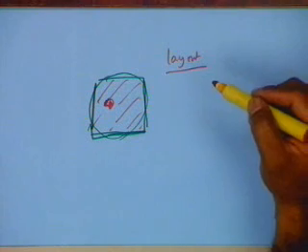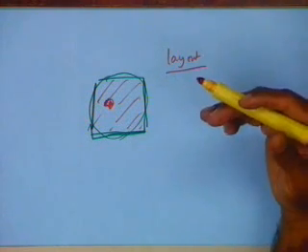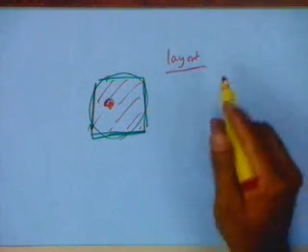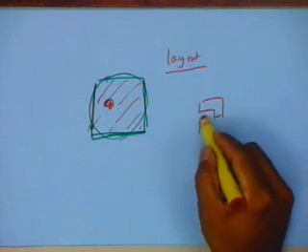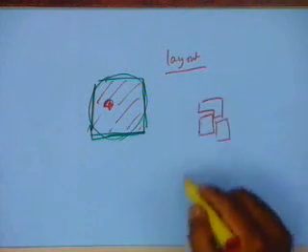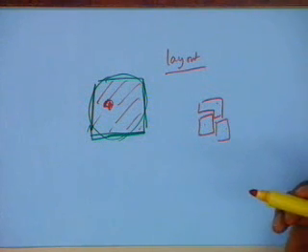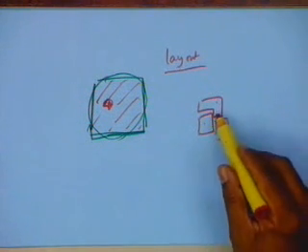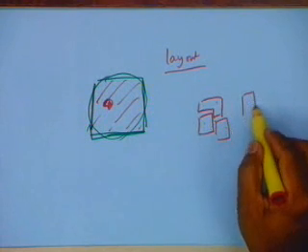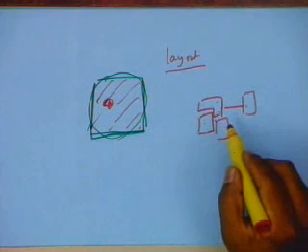So when you are doing the layout, see what is happening. Previously, when people did the layout, they were only interested in area and performance. You try to pack components closely together so that you can reduce the total area. People are also interested in packing things closely because interconnects take delay and you want to reduce the interconnect.